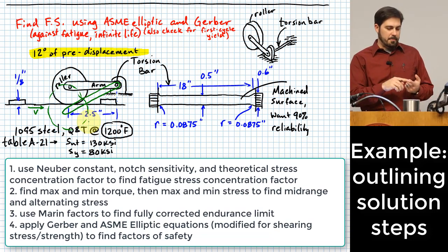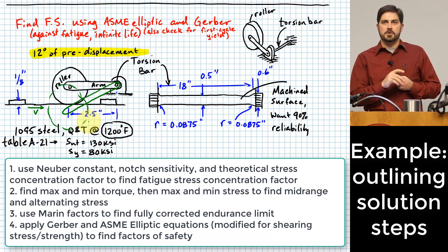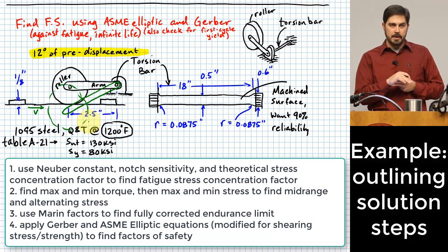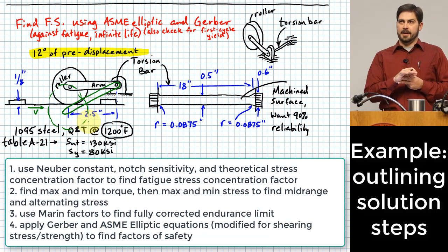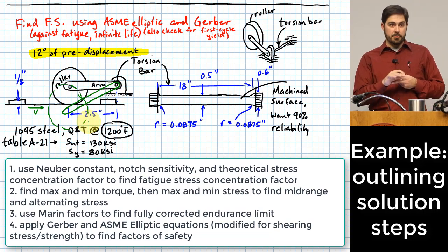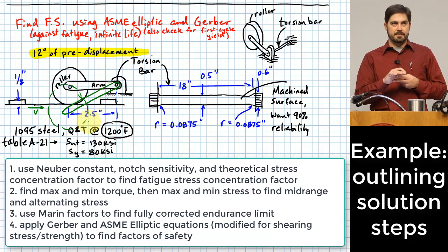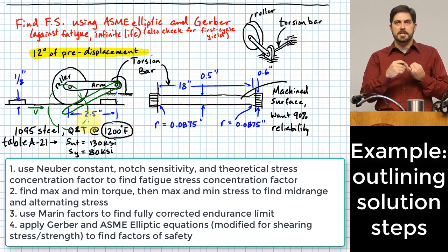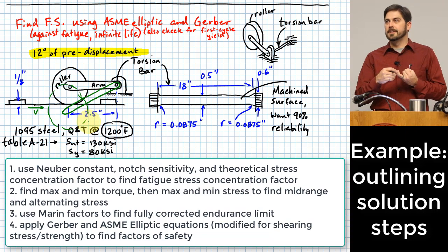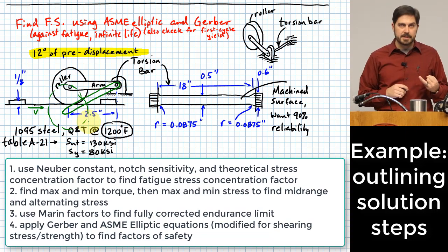Okay, we'll need to find our maximum and minimum torsional stress that we have here, the shearing stress induced due to torsion. We have to do that, and in order to get the max and min that we really want, what else do we need? We need a stress concentration, right? We need a fatigue stress concentration factor. That's another factor that we will need before we get this problem completed.